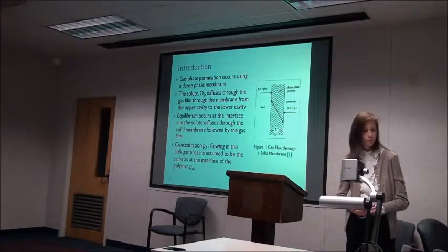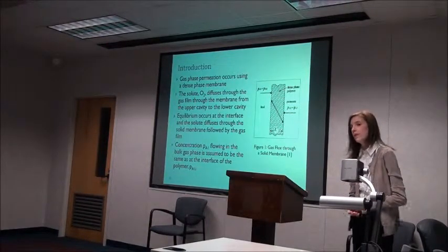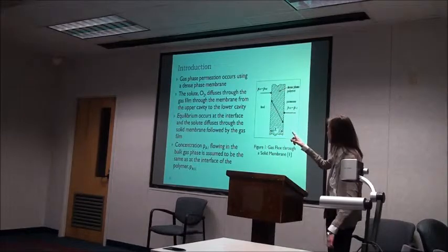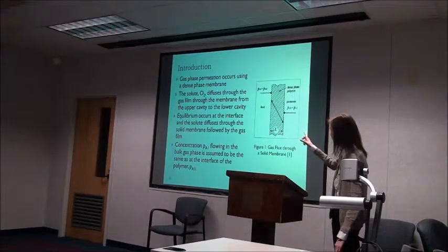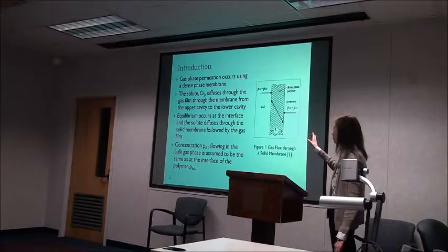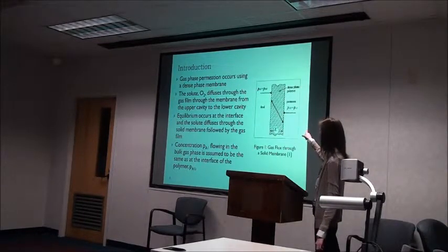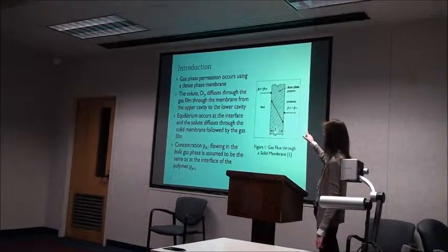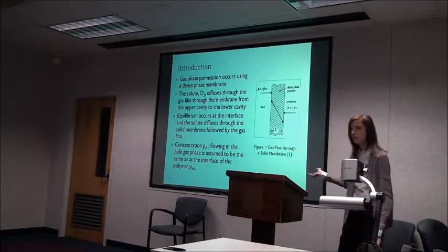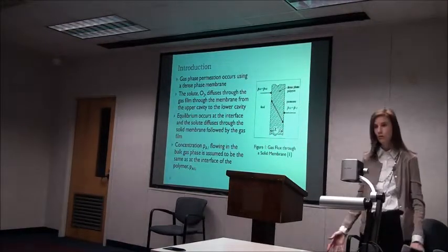the gas film. The concentration PA1 on the left is assumed to be equal to PA1I, which is the same at the interface of the polymer, and that's also true of the permeate. PA2I is equal to PA2, which is an assumption that makes the calculations simplified.